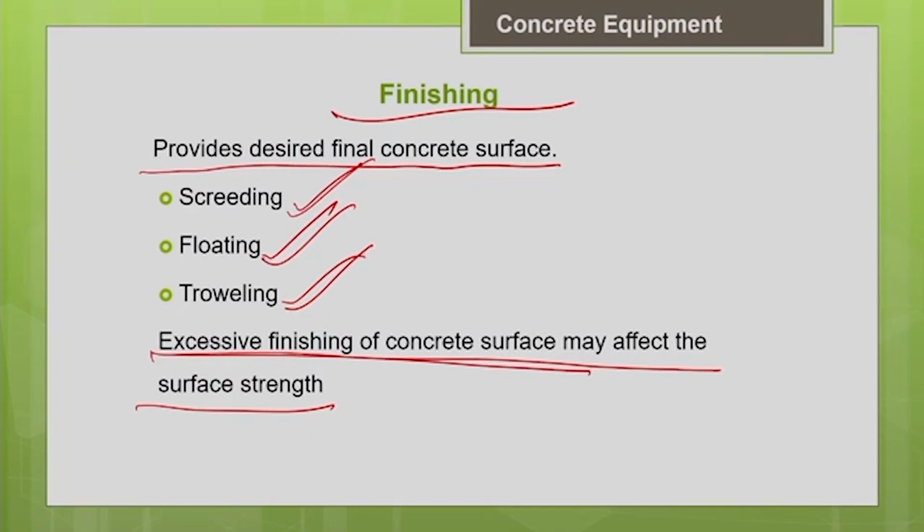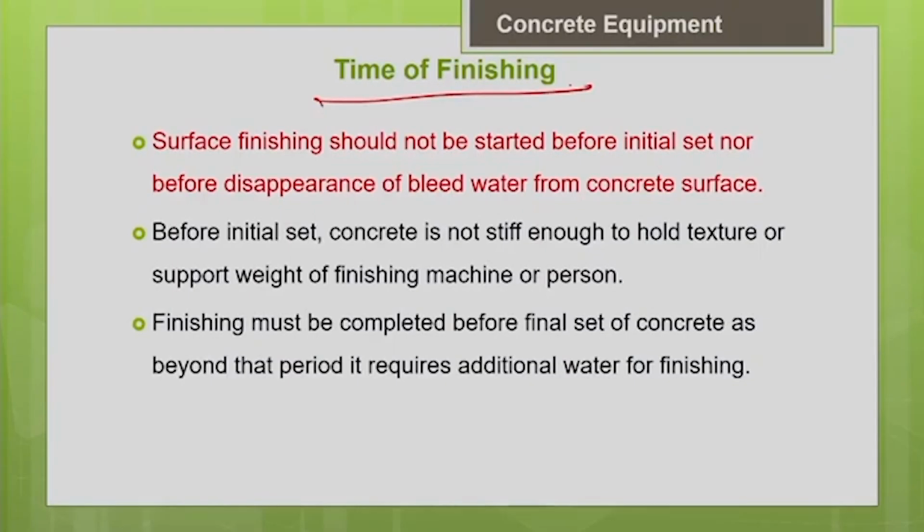Let us discuss the different steps of finishing one by one. The first thing we are going to discuss is the actual time of finishing. When should we start the finishing operation? The surface finishing should not be started before the initial set. Before the concrete attains its initial set, we should not start the finishing.